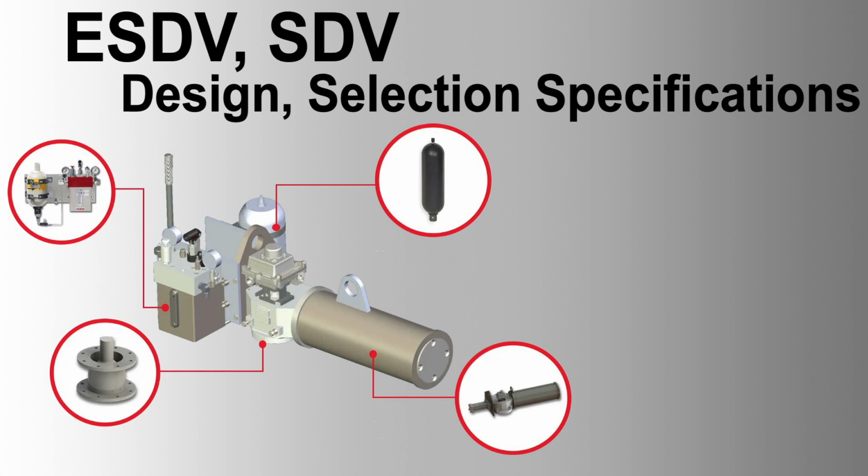Mechanical stops, adjustment: externally adjustable for opening and closing strokes, independent of valve travel stops. Speed control facilities, control: needle valves with vernier scales indicating closure times. Tubing: sized for stroking times and pressure ratings.